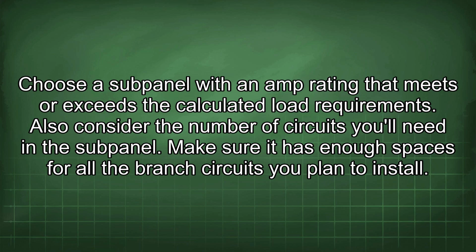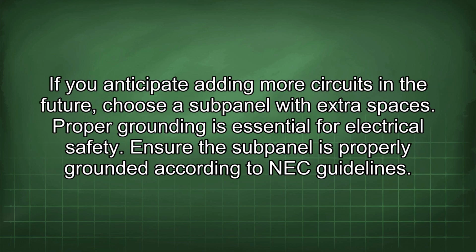Also consider the number of circuits you'll need in the subpanel. Make sure it has enough spaces for all the branch circuits you plan to install. If you anticipate adding more circuits in the future, choose a subpanel with extra spaces.